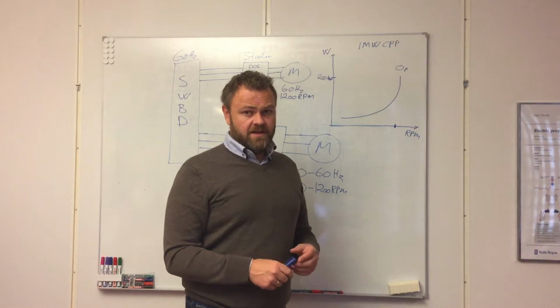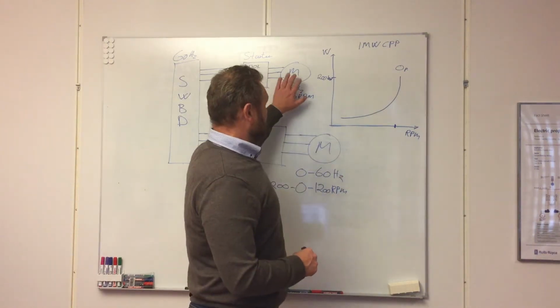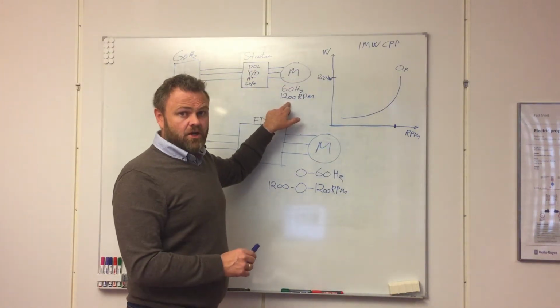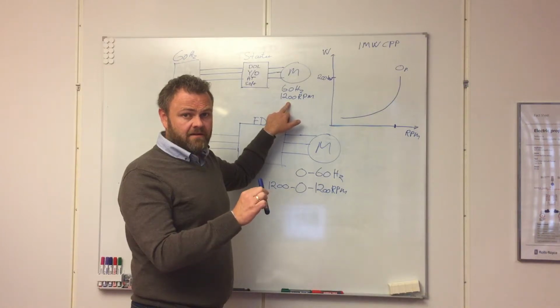And for a fixed speed propeller, as you have here, you need to regulate the thrust by regulating the pitch of the propeller.